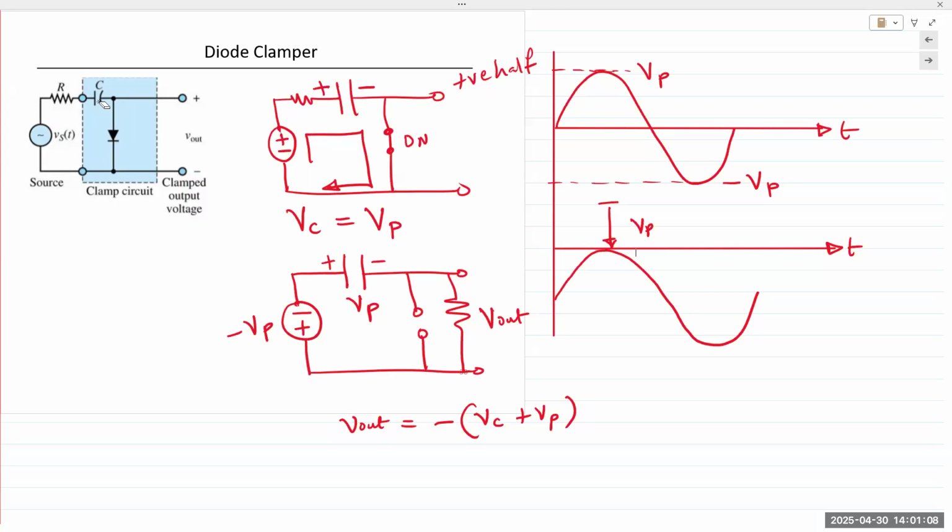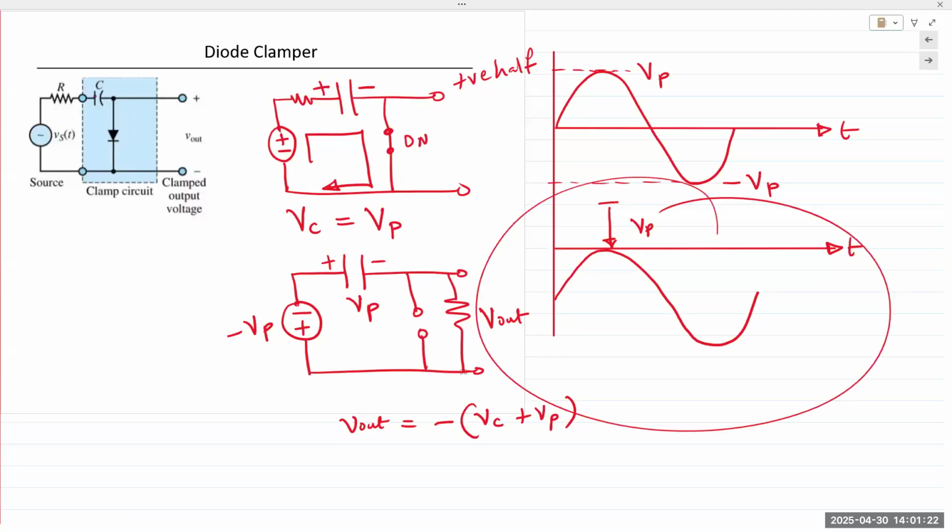There's a transient portion. By the time it goes from 0 to full, that's the transient analysis. But eventually it reaches the full charge, and then we obtain a waveform like this. If you perform this circuit in real life, it's really fast. Depending on the frequency of the waveform, it will take microseconds. You flip a switch on, and instantly you'll see a clamped waveform.